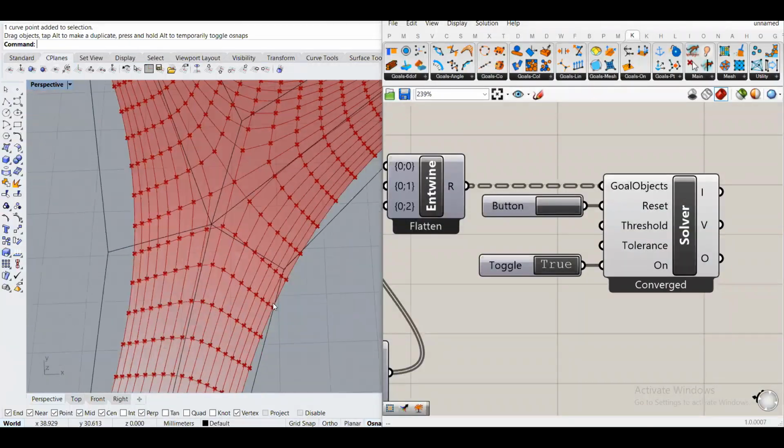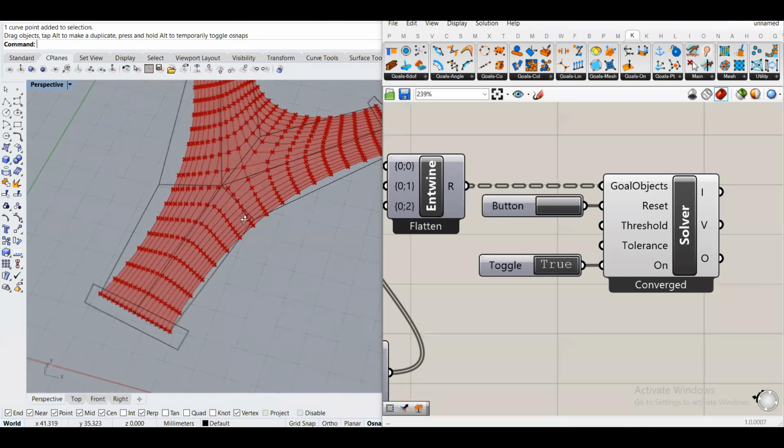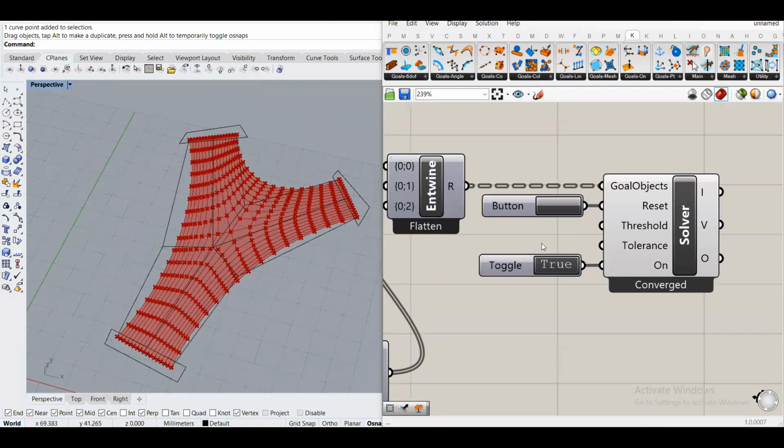So the way I work with it is usually I just go through. Oh, fixed it. Nice. But it's basically I just go through every rectangle and just make sure that everything kind of aligns. Grid snap, if you have grid snap turned on, it's really bad in this case, because it might kind of snap to the grid line rather than the endpoint and kind of mess up your whole structure. So make sure that grid snap is turned off.